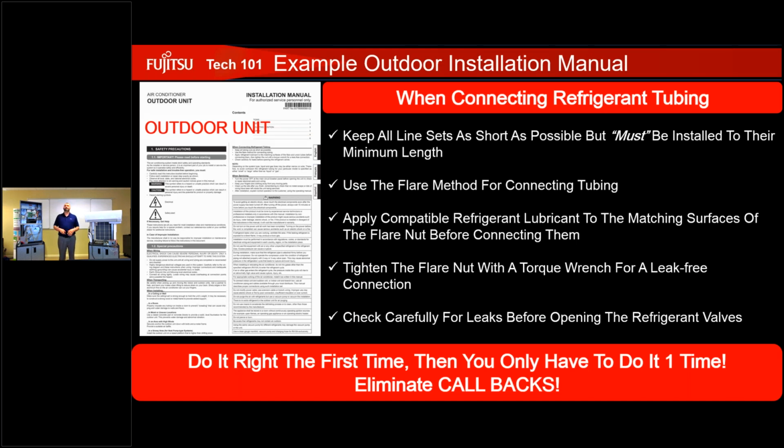All right, so always make sure that we keep all of our line sets as short as possible, but installed to the minimum length. Pretty simple there. Always use the same flare method for connecting our tubing. Only use the compatible refrigerant with the system. In this case, most cases, it's going to be that R410A until they decide to change it on us again, which is probably coming soon, I would imagine. They like to throw wrenches at us from time to time.